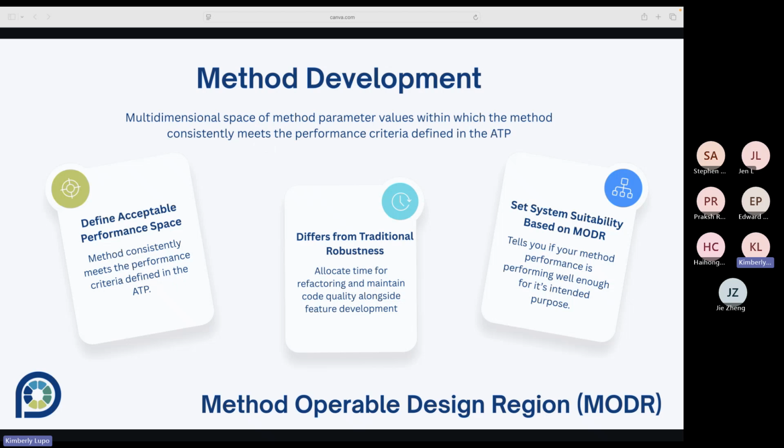So that brings me to system suitability. And this is an area where I think we all could do a lot better. The traditional approach to system suitability criteria is somewhat circular and often arbitrary. You run your validation, you observe the performance you get under optimized conditions, and then you set your system suit limits based on what you observed, typically adding a small margin. The result is system suitability criteria that tell you your method is performing the way it performed during validation under controlled conditions. What they don't necessarily tell you is whether your method is performing well enough to deliver reliable results